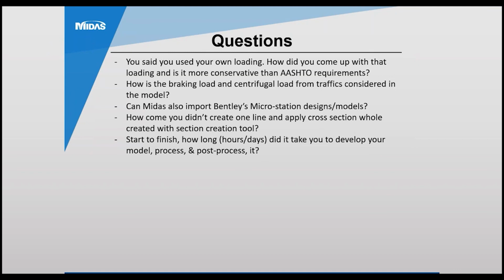You mentioned that you computed the elevations at each support outside of MIDAS. How did you import those elevations into the model? Okay, so we calculated those, and then, it's the advanced button for the multi-curve. Inside the wizard, there's a little section at the bottom. It's just a hand input. So we had to calculate how far along the center line the support was for a station input, and then we just entered the elevation by hand in the box in the wizard.